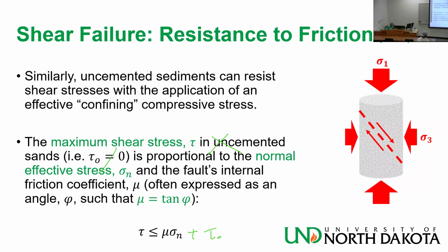So the biggest tau would be the one from the biggest difference between the stresses. So sigma 1 and sigma 3 will yield a bigger tau than sigma 2 and sigma 3, or sigma 1 and sigma 2. So the Mohr-Coulomb failure criterion has this simplification, idealization, or assumption that it doesn't care about sigma 2. It only cares about sigma 1 and sigma 3.